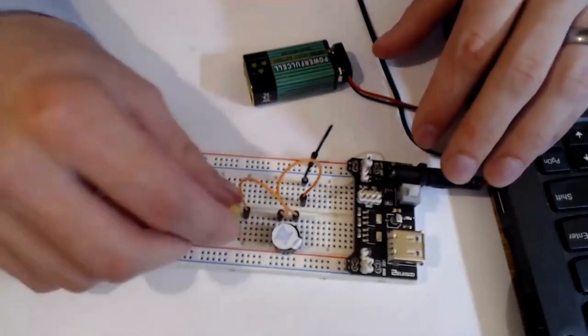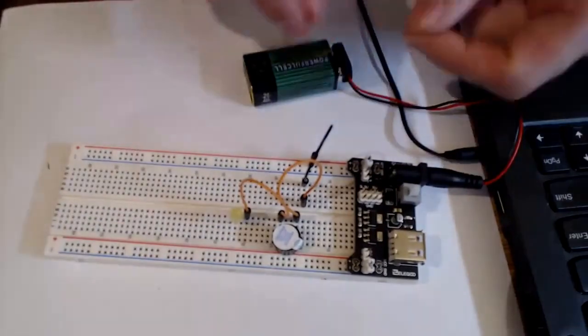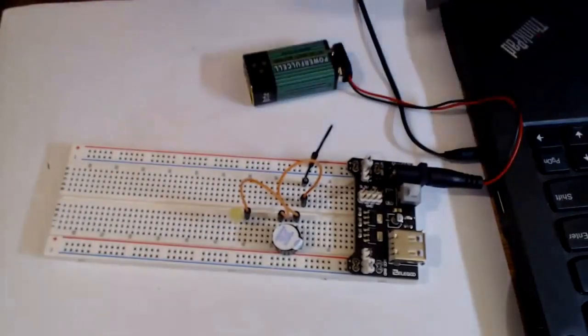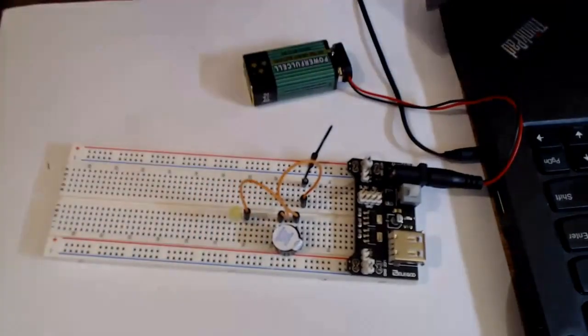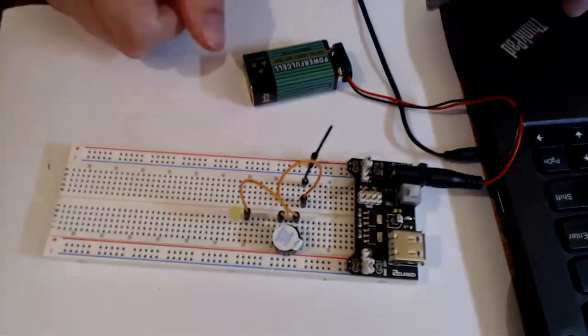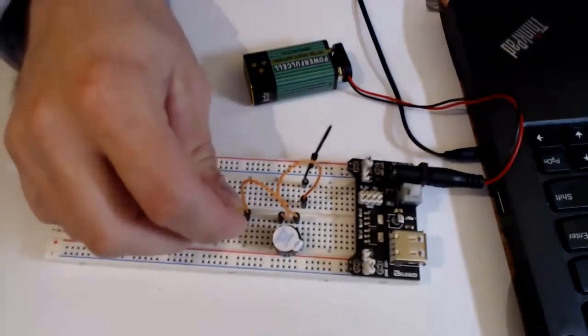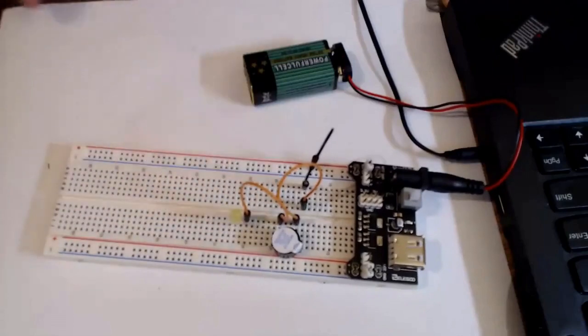And be a little careful pushing these things in. You have to sometimes bend the leads a little bit to get them into the holes, and then you have to be careful pushing them in that you don't bend them further. There are quite a lot of delicate little parts here, but you still need to push them in enough so that they don't just fall out.